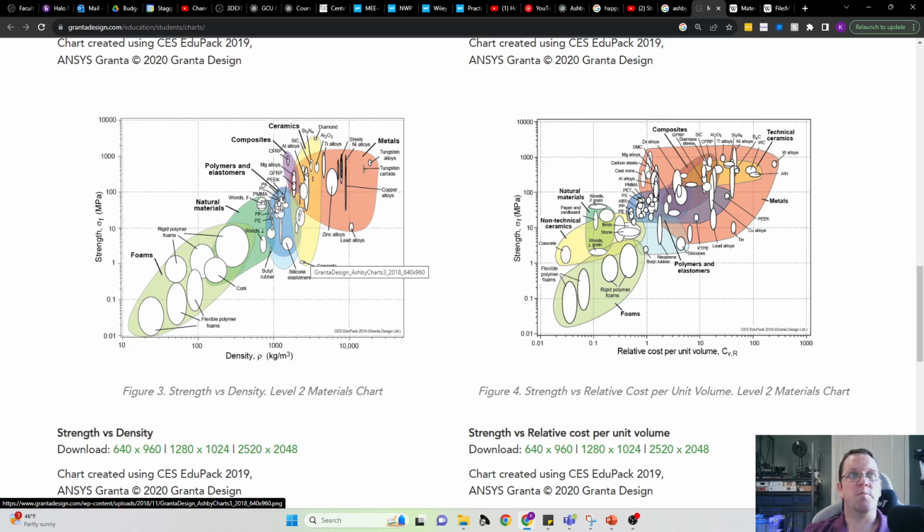So a lot of polymers, especially engineering grade polymers, PEEK and polycarbonates and things like that, PMMA, these are things that we can build stuff out of that are fairly lightweight, but also fairly strong, and that's why we do that. Wood, of course, because of cost and other things, we'll look at on the next chart, can also be a factor. So an Ashby plot is comparing some property of a material on a log scale with some other property of material on a log scale.